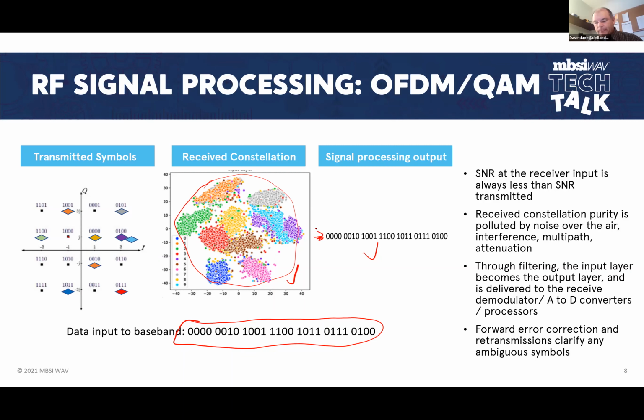How's that done? Well, first of all, we use something called forward error correction here. 1 or 2 or 3 of the bits that are sent over the air, depending on what our modulation level is, may be used to generate a checksum for our forward error correction. So the transmitter knows what the data coming in is, divides it by the key, and then the modulus is sent to the other end. This end knows how to do the same math on it again.